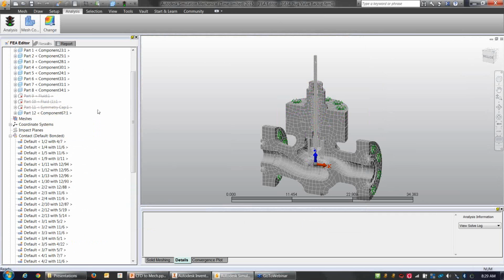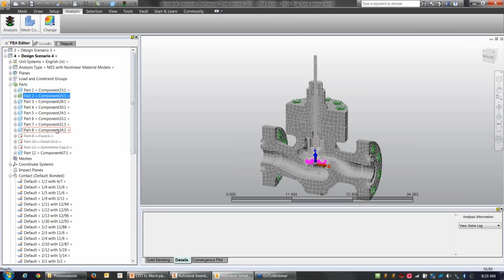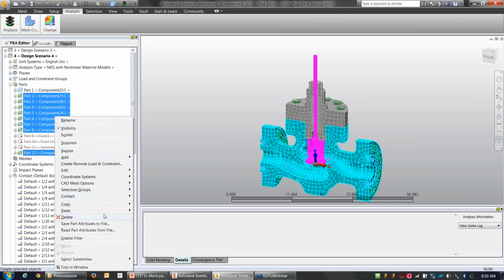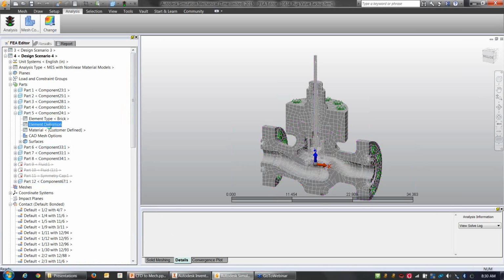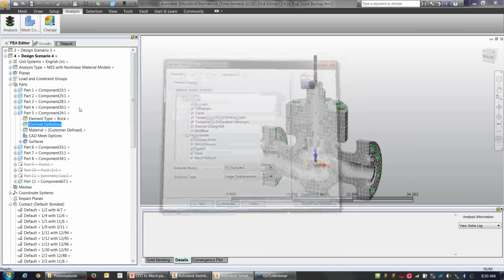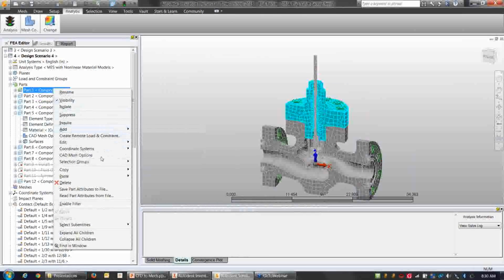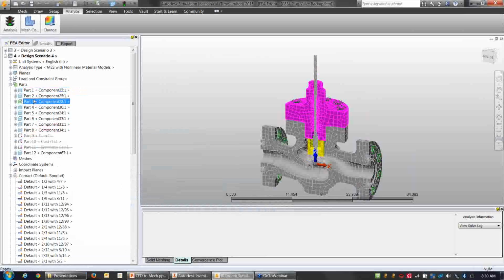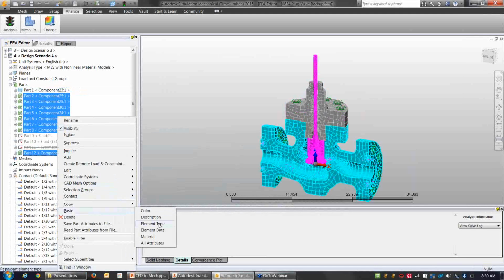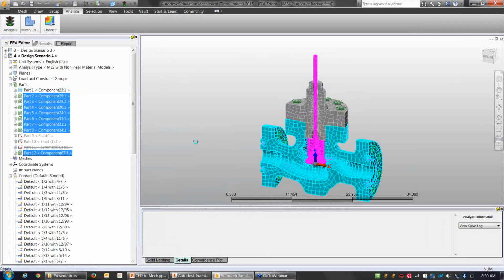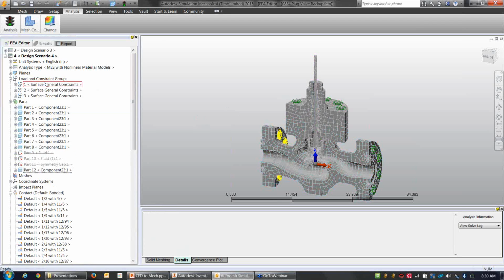Let's see. So I'm just pasting all the... Well, you probably wanted all attributes since this was set as temperature dependent. Yeah, thank you. Let's just go all. Yeah, I forgot. Modify the element definition. There we go. Loads and constraints, surface.